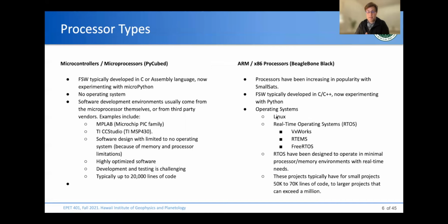And if you really need that more real-time capability, you can install some other operating system, like a real-time operating system, such as VxWorks, RTEMS, or FreeRTOS. These are quite common in the aerospace industry. RTOS has been designed to operate in minimal processor and memory environments. So actually RTOS or FreeRTOS and RTEMS, some of them will work in microprocessors, not necessarily microcontrollers. So there's some back and forth here with these real-time operating systems.